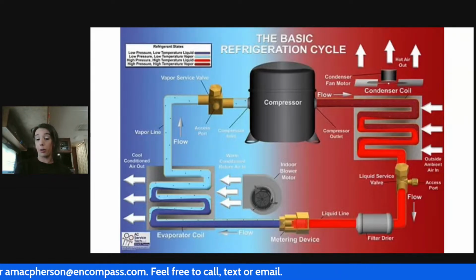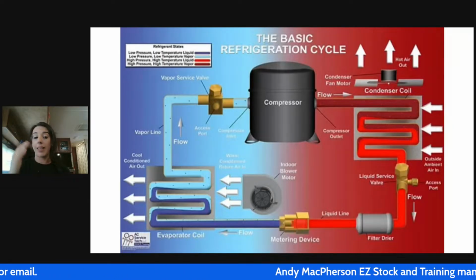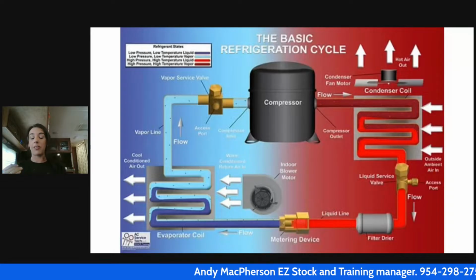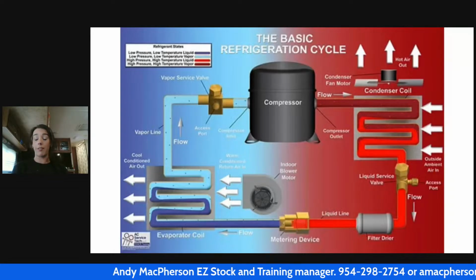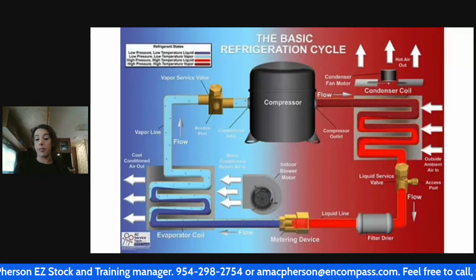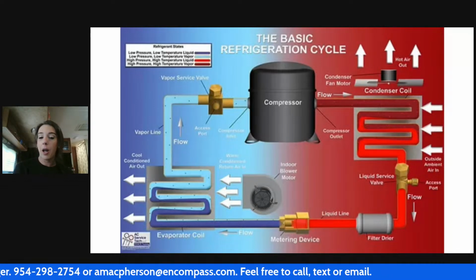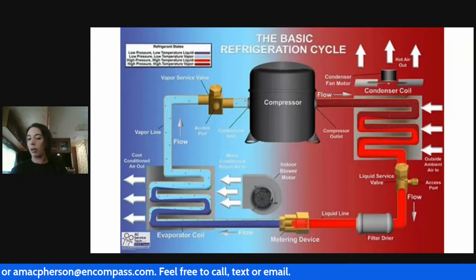That gives us another clue. So if we have low evaporator temperature and high superheat, that means that we're not saturating at the correct spot. That means that we are very, very low on refrigerant for one reason or another in the evaporator. So again, two puzzle pieces that are given directly to us on a silver platter that we can use together, but using them separately might not be a great idea.